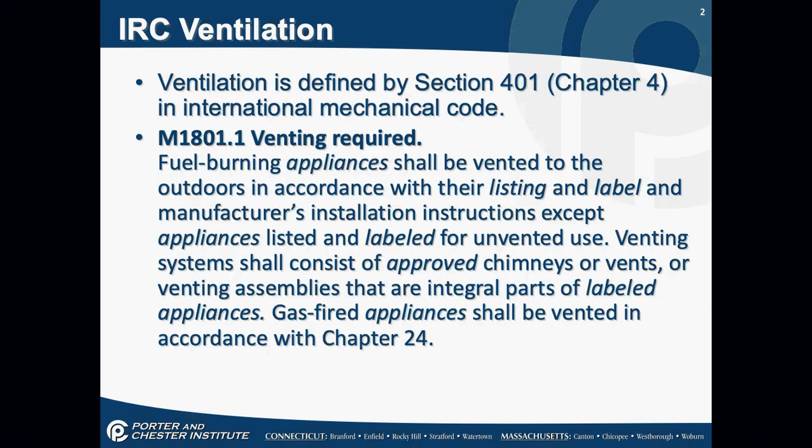Fuel-burning appliances shall be vented to the outdoors in accordance with their listing and label and the manufacturer's instructions, except for those appliances labeled for unvented use. Venting systems shall consist of an approved chimney or vent, or venting assemblies that are integral parts of labeled appliances. Gas-fired appliances, they refer to another chapter. I'm not worried about that right now.